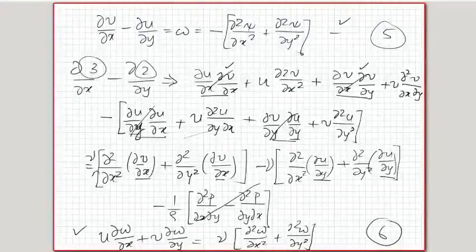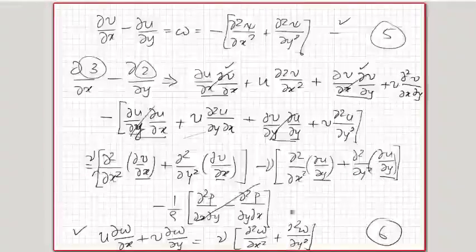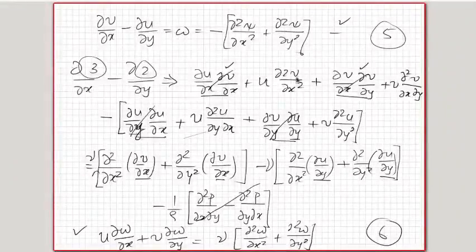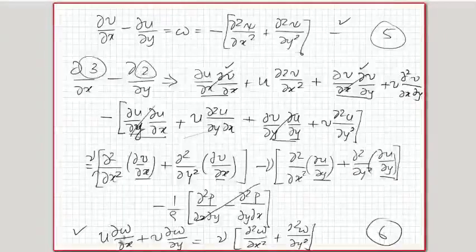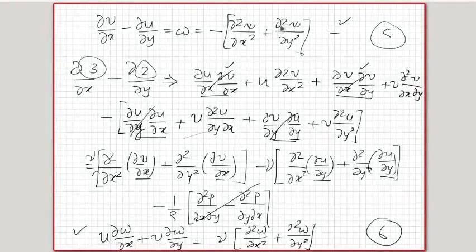But as of now, in the stream function vorticity method, we will just leave it like this. You guess a value of psi, and using that value of psi, you calculate u and v and solve this equation. You get a value of omega, put those values of omega into this and get the values of psi, and differentiating the values of psi, again you get u and v. So simultaneously solve and iterate. Okay, so that is the process that you will do. So let me just write that method.